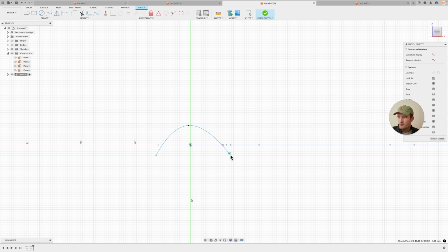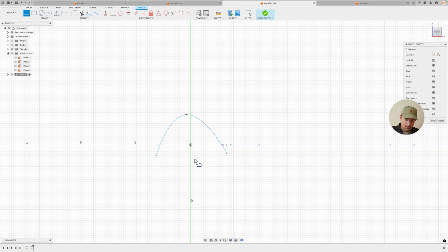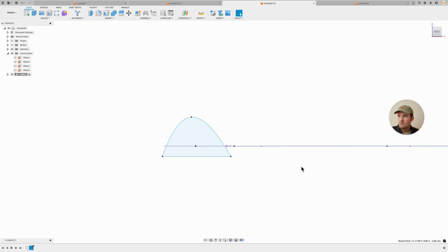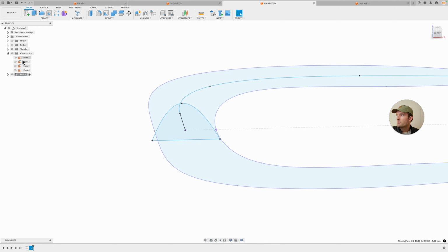So what I'm essentially going to do is make a loft, and I'm going to split it in half. So you essentially just want this to extend below this plane. I'm going to split it along this plane, and just want to make sure that everything is under that so that we can have a nice flat surface. So that's our first one.